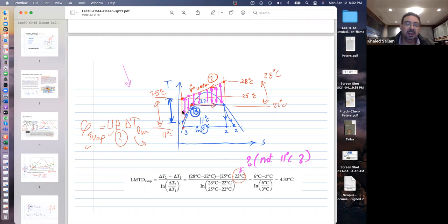So as I told you earlier, one of my friends actually worked for a big bus company that designs and constructs buses, and specifically HVAC equipment for big buses. And the customer would come and say, well, design the heat exchanger for this small delta T. Again, they want to make sure that the heat exchanger is really big so that even if you run with this small delta T, it will work. And you will tell them this is too conservative. We really have a little bit bigger delta T. We don't have to have all that heat exchanger on top of the roof of the bus. We can make it smaller because a realistic delta T is actually this, not this. The same idea, right?